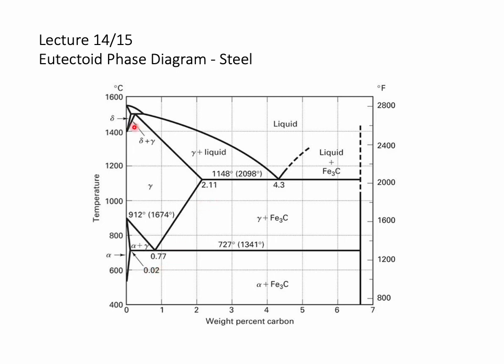There it is. Okay, so this is the iron carbon phase diagram. We have a liquid phase up here and a eutectic reaction where the liquid is transforming to two different solids, gamma iron and Fe3C. That reaction when liquid goes to two solids, that's a eutectic. We also have, and the focus of this phase diagram is, a eutectoid phase reaction where gamma phase on cooling transforms to two different solids, alpha and Fe3C.